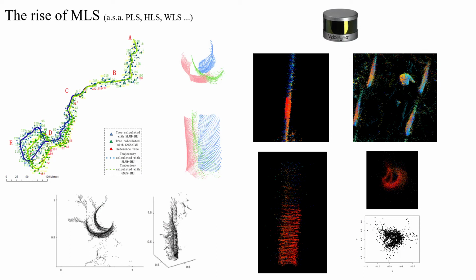And the first attempts to apply SLAM inside the forest environment, they were quite good globally, but the SLAM algorithms, they suffer from a few pains, let's say. If you scan for a long time on very long paths, your point clouds might drift, so you have a very good localization in the beginning of your walk, but by the end of it, you have drifted to somewhere else. And globally, it looks really consistent, but when you zoom into the objects you're trying to measure or segment, you see there are some localized inconsistencies. Like some trees maybe don't match, some diameters that should be on the same spot, they are not exactly there, they drifted a few centimeters apart. So it's not really good for applying this on high precision forest inventory.